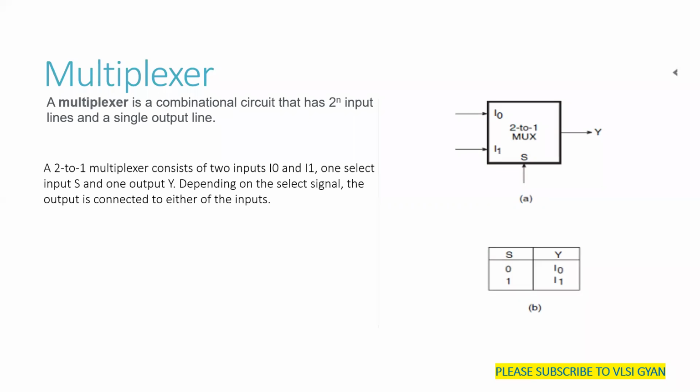Suppose you have a multiplexer and you want it to work as a gate, then what should you do? So this is the implementation of gates using a multiplexer. We don't have gates, but we want a MUX to work as a gate. So MUX is a very simple combinational circuit, friends, which can be used in many ways.